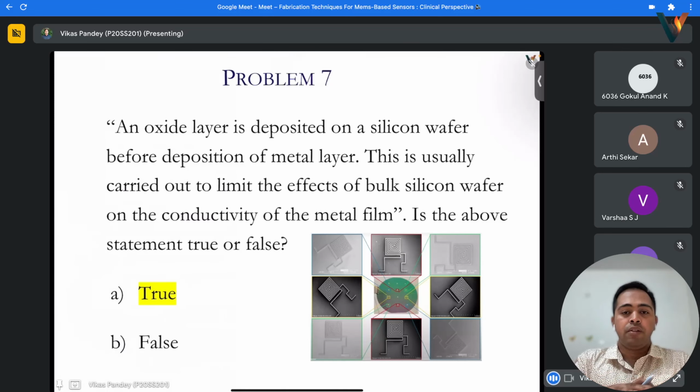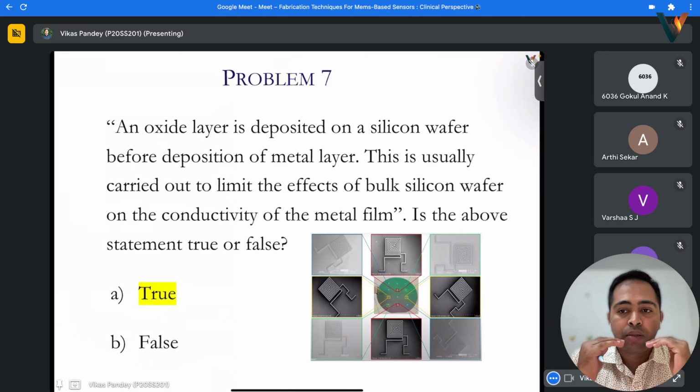But above it we make depositions of maybe 200 300 nanometers. For a 200 300 nanometer layer, this whole 300 micron will be very thick, and it will take part in the whole process. To isolate it, some insulation layer is used, maybe 400 500 nanometers or 1 micrometer.